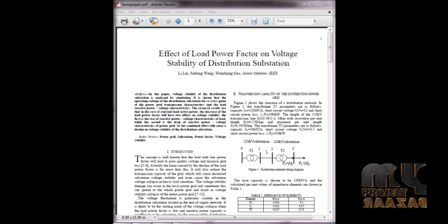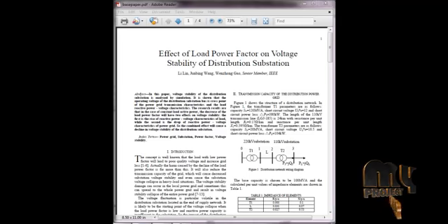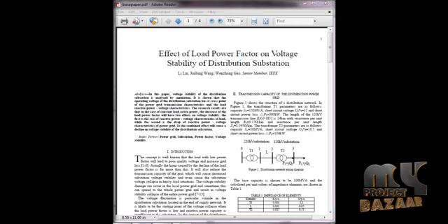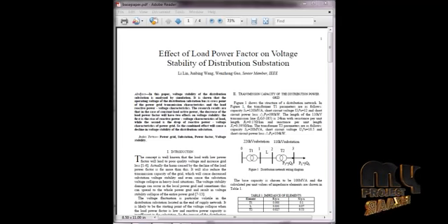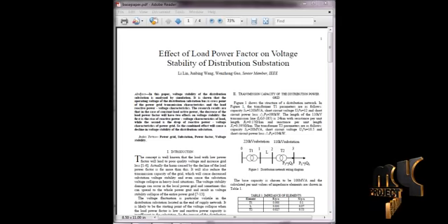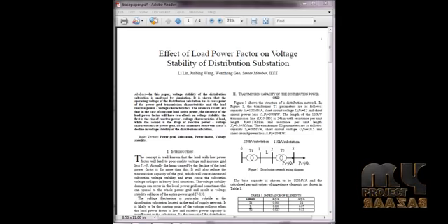The equipment normally used for the voltage and reactive power control are on-load tap changer transformers, switched shunt capacitors and step voltage regulators. Such equipment are mostly operated based on the assumption that the power flows in one direction only and the voltage decreases along the feeder from the substation to the remote end.